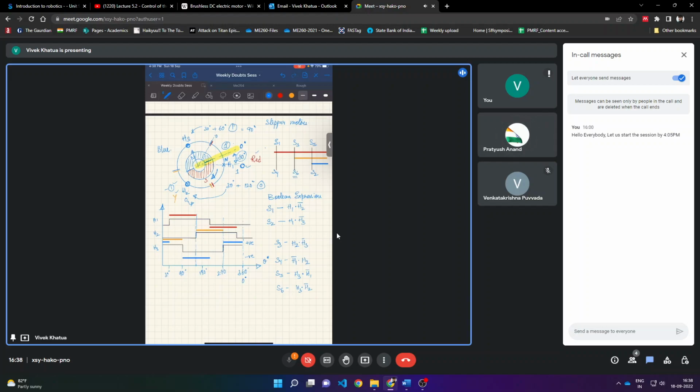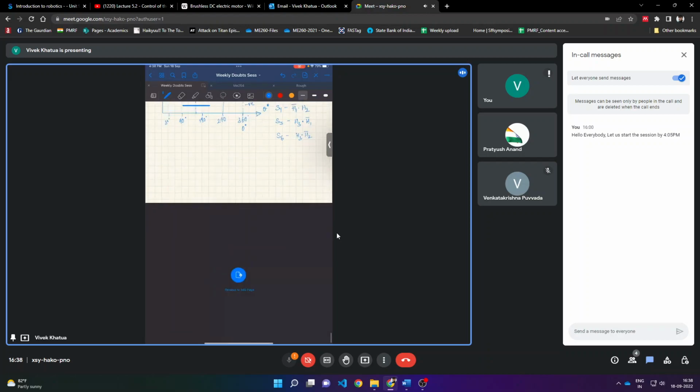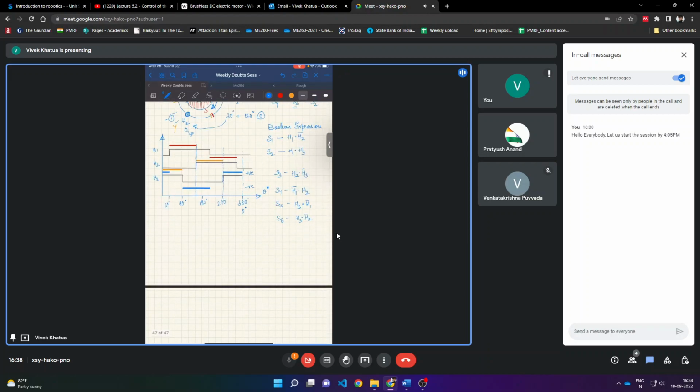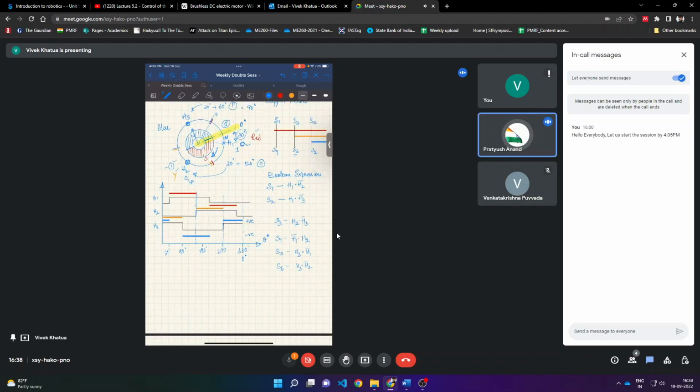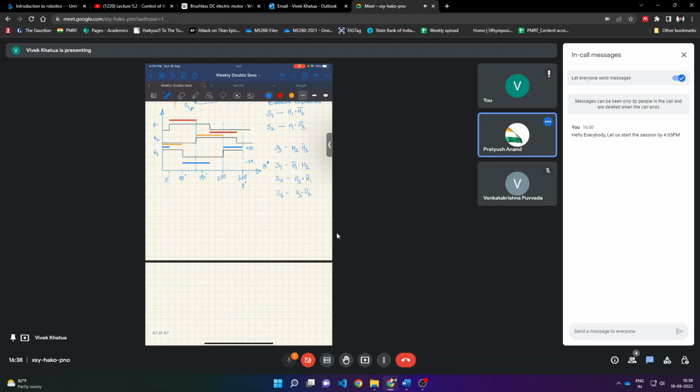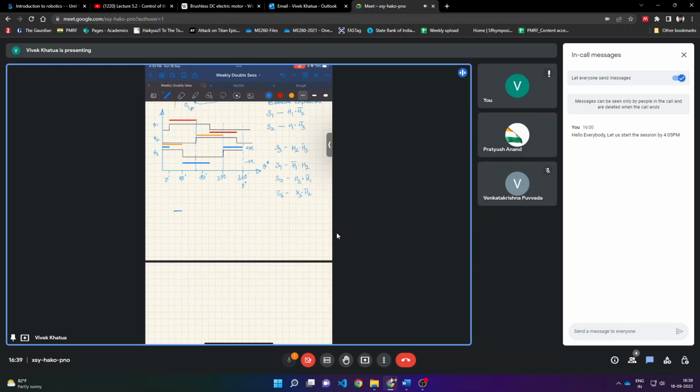So when I keep on rotating, the Hall sensor is going to give me a perfect one for the next 180 degrees, because my north pole spans a complete 180 degrees. For the initial 30 degrees there is nothing, and then for 120 degrees, how will it look?